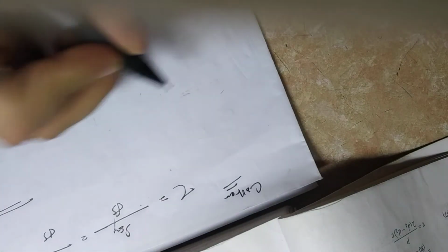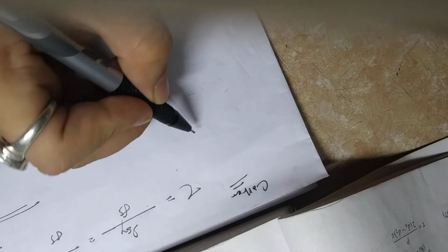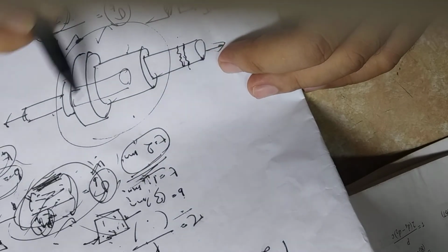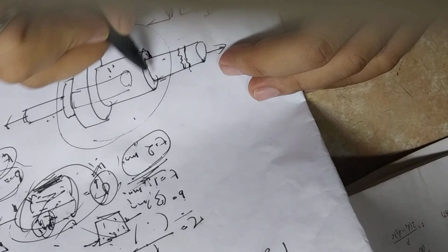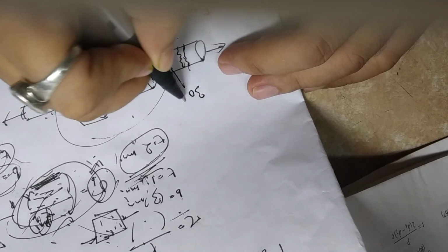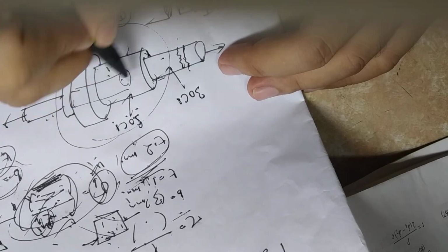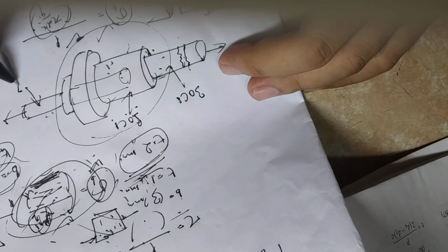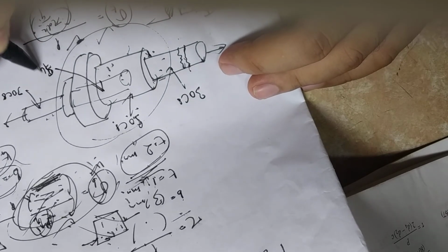Now let's find out using that formula. Sigma T for the rod: since the Cotter is a part of the spigot or socket, both are integral parts of the rods, isn't it? And rods are made of the same material. If this rod is made of 30C8, the socket will also be made of 30C8 because they are the same material. Similarly for this rod, 30C8 is the material, and the spigot part is also made of 30C8.